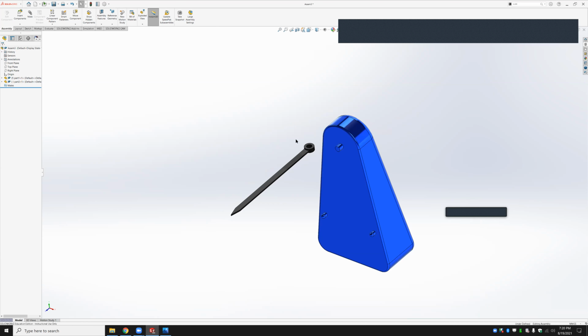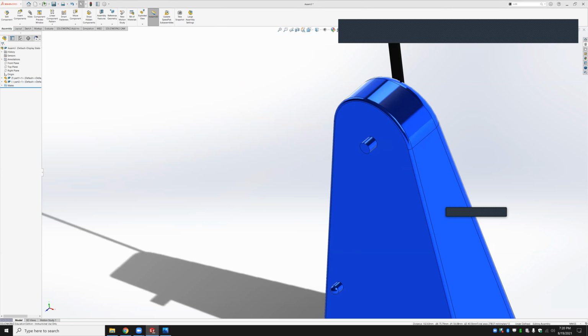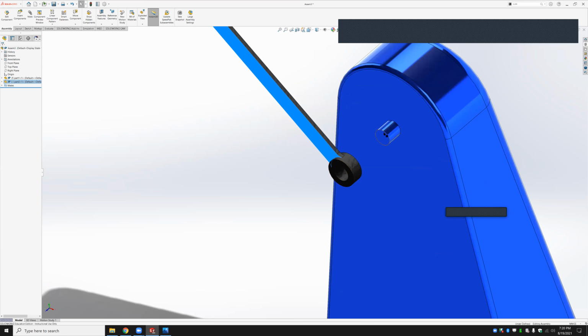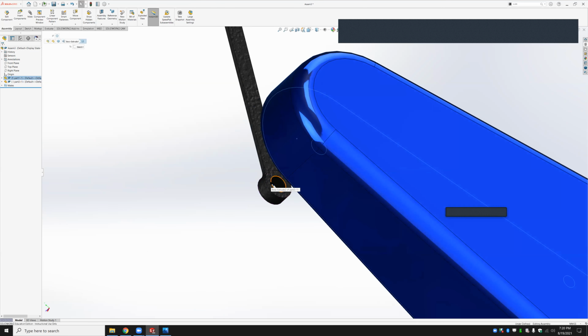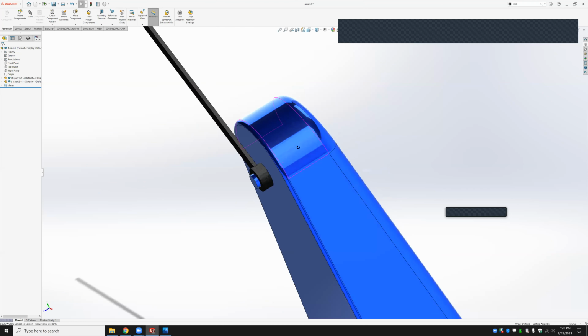Phil, you can do this problem. Good. You're saying suggestions? Yeah. Just concentric, right? You can do concentric. And then what would you do from there? So I'll do that. Concentric. And then probably line up the coincident as far as the plane, the back plane of that, front plane of that. Those two are coincident. Okay, that's one option to get the needle on there.